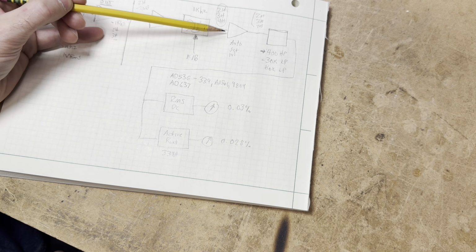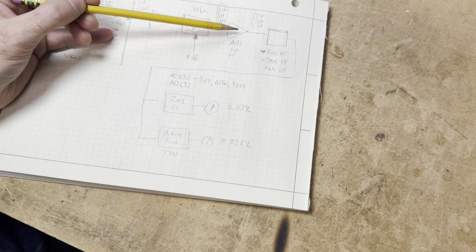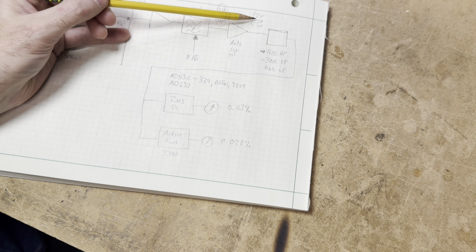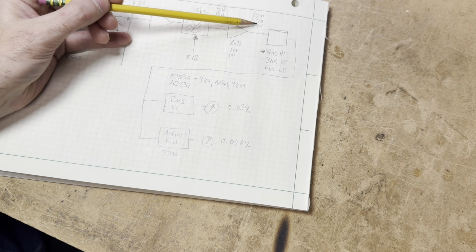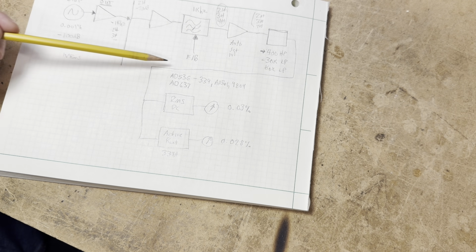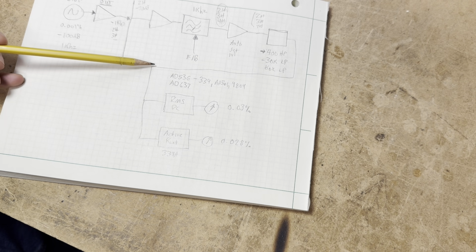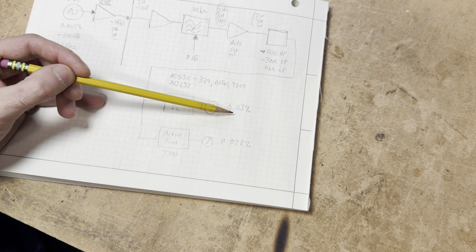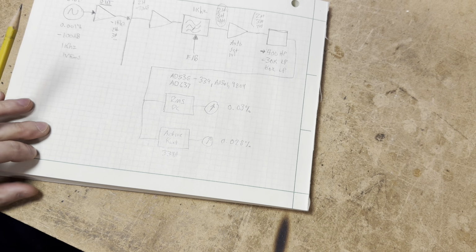We readjust that output to correct for level variations in the system so that the level of our harmonic components is the same here as it is at the input. Then we apply any filtering, and then we finally use some summation to add all of those components together and come up with a distortion measurement.